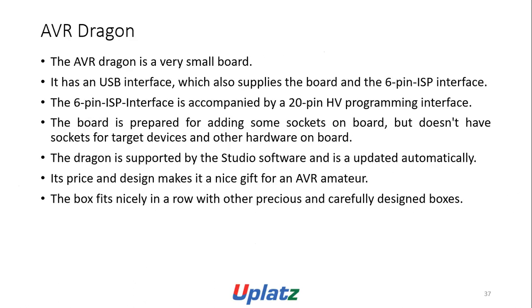AVR Dragon. The AVR Dragon is a very small board. It has a USB interface, which also supplies the board, and the 6-pin ISP interface. The 6-pin ISP interface is accompanied by a 20-pin high voltage programming interface. The board is prepared for adding some sockets, but does not have sockets, target devices or other hardware on board. The Dragon is supported by the Studio software and is updated automatically. Its price and design make it a nice gift for an AVR amateur. The box fits nicely in a row with other precious and carefully designed boxes.